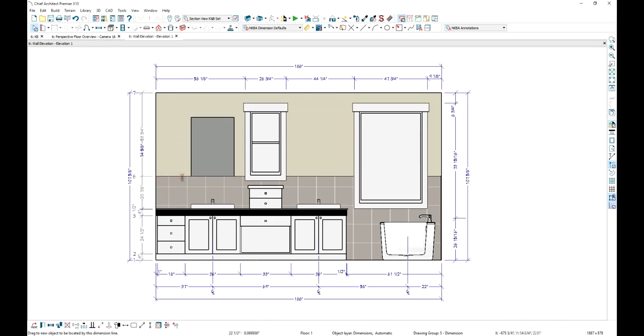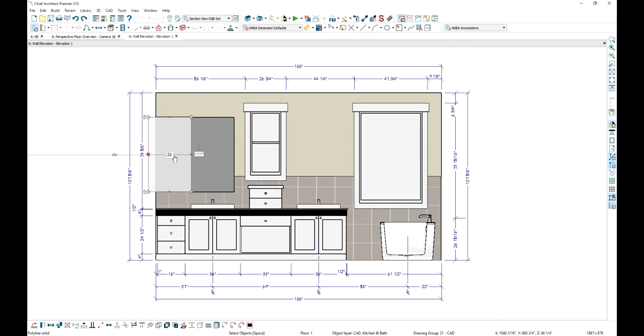Let's position it with our dimensions. Let's drag our dimension over here. I'm going to create one copy of this. Let's use the copy tool, slide it over. And with a temporary dimension, let's slide that into place. Probably set it at something like 4 inches in width. And while that object's still selected, let's use the copy and reflect around, again, that cabinet. And now I have the two components that I need.